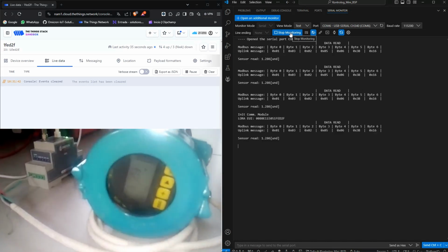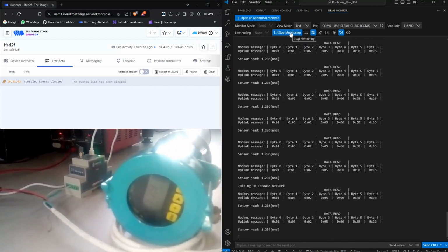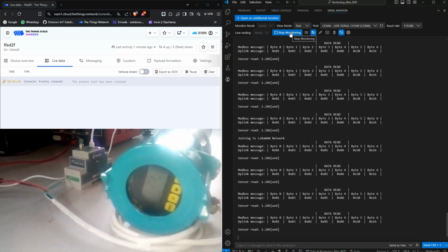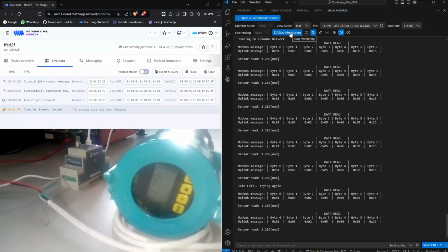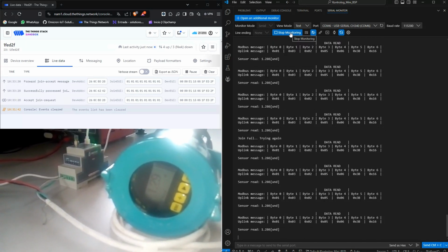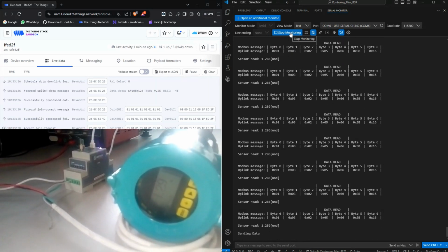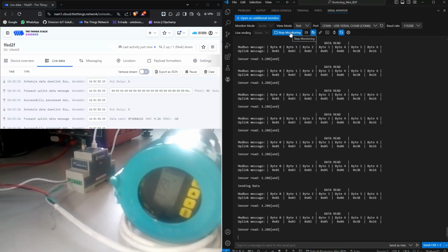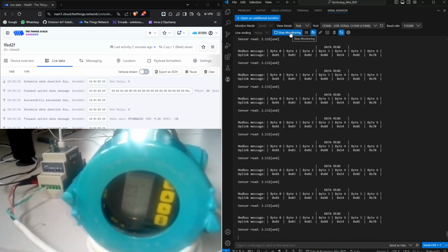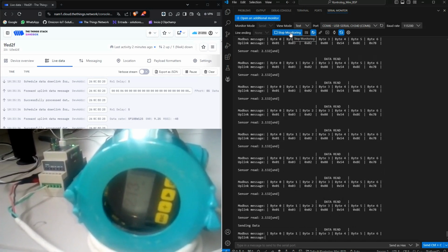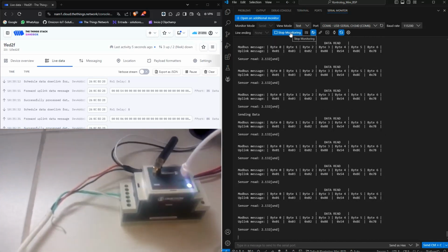In our case, the ContraLog Mini is linked to the ThingStack LoRa backend, where we can verify the reception of the message sent from our ContraLog Mini, where it is expected that we only see in the cloud server the bytes corresponding to the information collected by the sensor, and that have been added to the second and third byte of the uplink message. We cover how to link your ContraLog Mini to the ThingStack in a separate video. And that's it. You have successfully learned how to read a sensor using the Modbus RTU communication protocol and send the data to the cloud using LoRaWAN wireless communication technology.